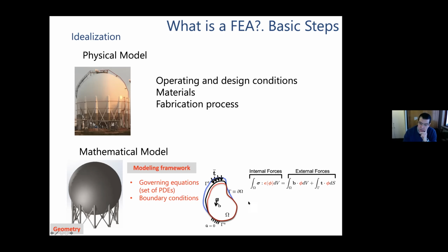However, this epsilon that you see here in the principle of virtual work corresponds to, in a deformable solid, for instance, we can distinguish between the unstressed or undeformed configuration that is given by this blue line, okay? That corresponds to the shape of our body without any loading applied to it. So when we apply the loads, this body will experience a deformation, and then will move towards a deformed configuration that is indicated by the black line here. Moving from the blue line to the black line implies that the body will be deformed and that a set of stresses will be generated. So you can imagine that the stresses appear as a consequence of the deformation of the solid, which is deforming due to the action of external forces.